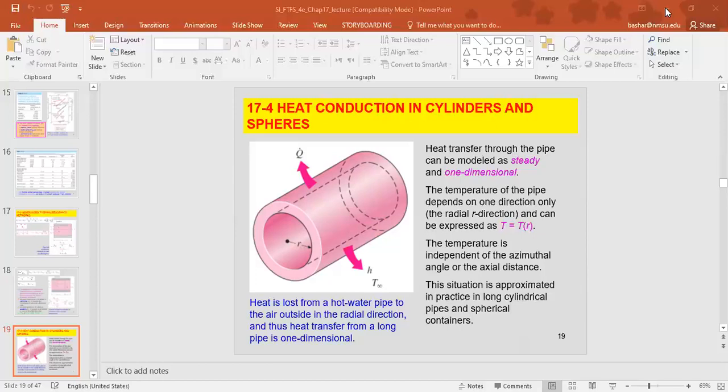According to the energy balance, the heat transfer by convection equals the heat stored in the body. That's represented by this equation here. h A_s (T infinity minus T) is the heat rate by convection, and that equals the heat stored in the body, m Cp dT/dt. The mass may be represented in terms of the density and the volume, as we all know, rho V. We may introduce T minus T infinity to replace dT, and so dT will simply equal d of (T minus T infinity), since T infinity is constant.